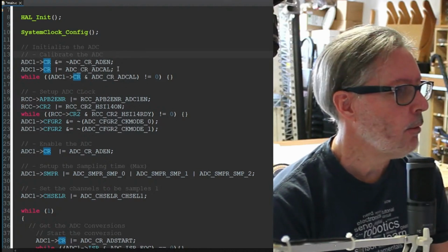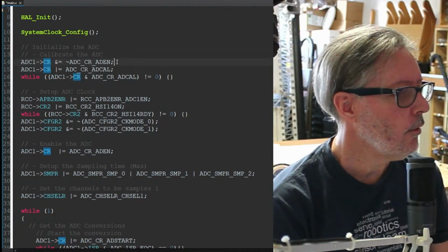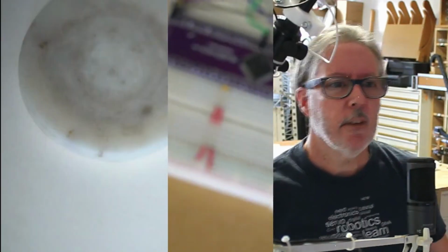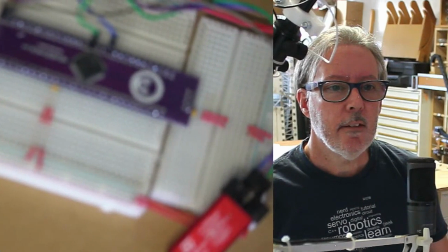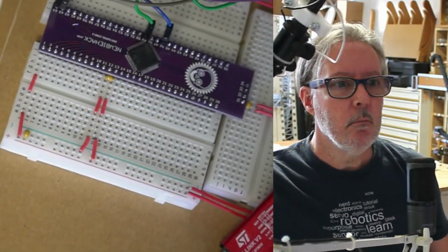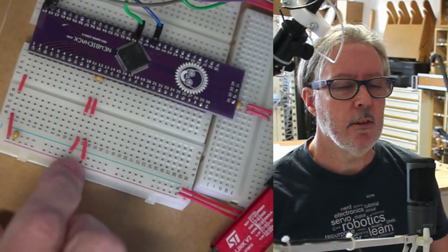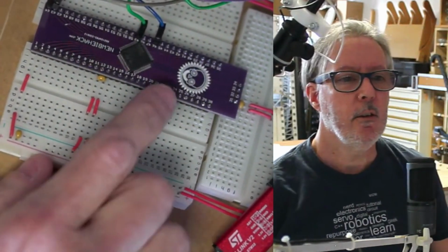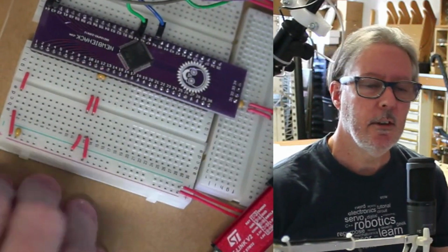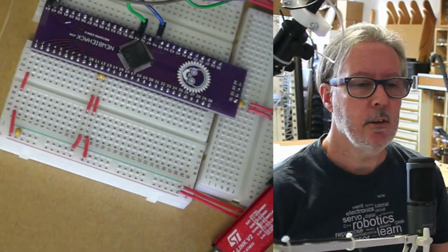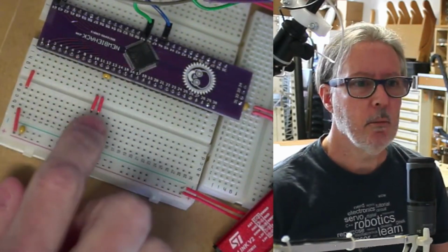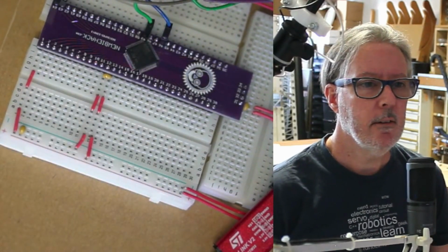So it's calibrating it probably to the reference voltages that are on. That's interesting. Why is it showing this? I will do that then. That's odd. Okay. So the reference voltage is going to come from, most likely, there's also a reference voltage pin that you can use to adjust the reference voltage. But the reference voltage is the span of voltage that you will be using for the ADC. I think if you're not using the reference voltage, it probably uses the voltage here as a reference.